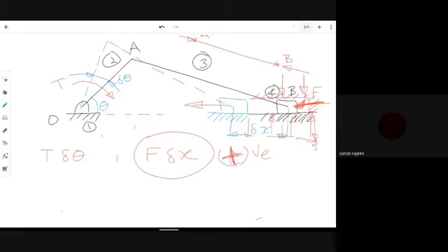Now, what about this side when the torque is acting? Basically, the displacement that is happening to link number 2 is in the anti-clockwise direction. Hence, the applied torque should be in the clockwise direction so that it stays in static equilibrium. That means the work generated here is negative. So ultimately, we can say that the work generated by the force F is positive, but the work done due to the torque T at link number 2 is taken as negative.